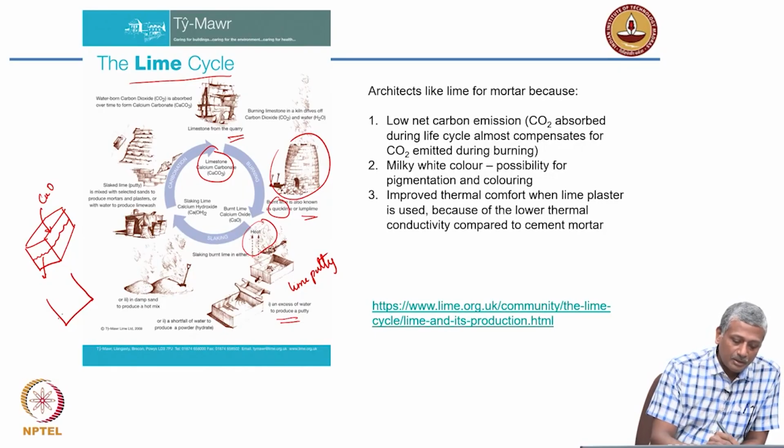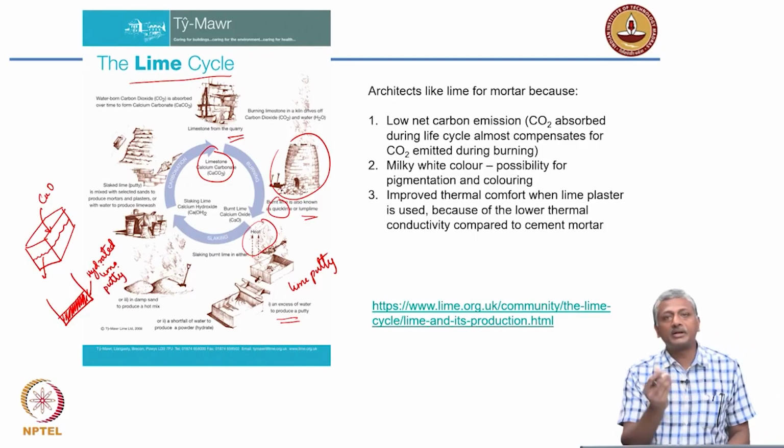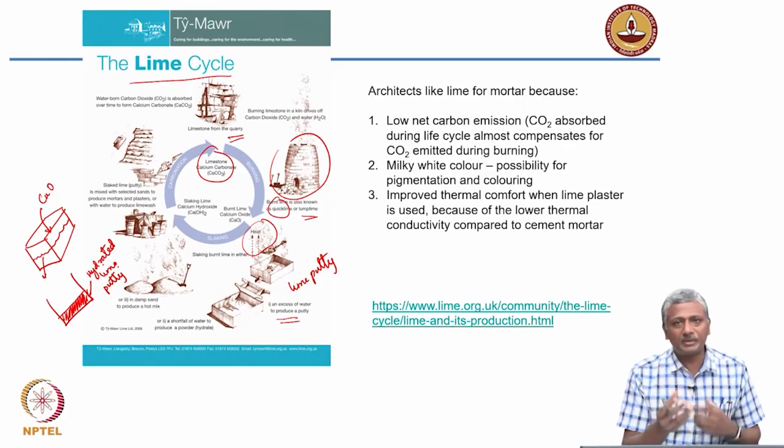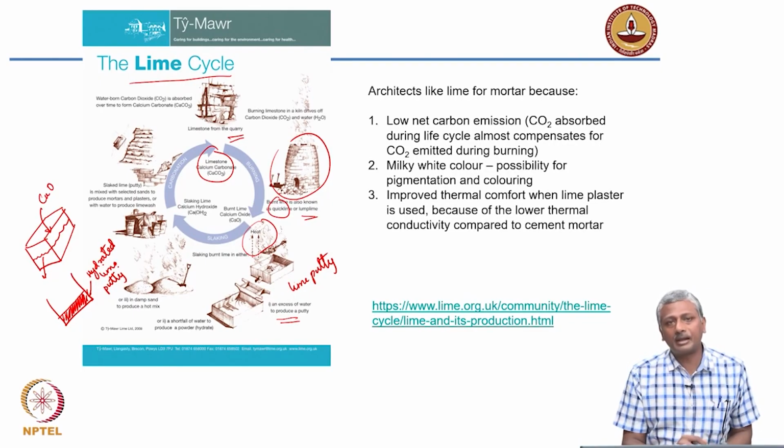At the bottommost part, you form a nice plastic hydrated lime. All the lime gets hydrated ultimately, but what is in the bottom is called lime putty. Lime putty has a nice plastic nature about it, and you can mix it nicely with mortar, sometimes adding some extra water to make your lime mortar.